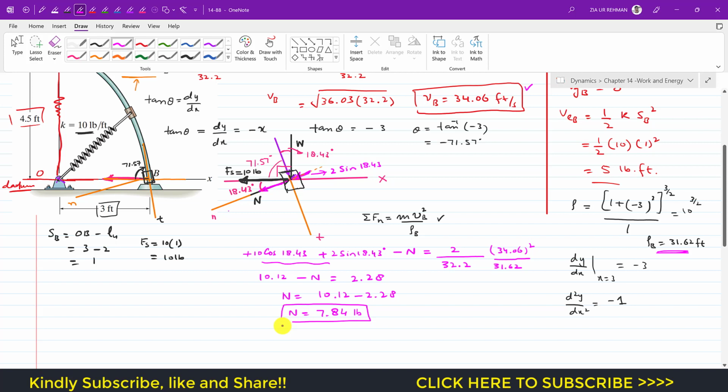Now similarly, if we apply the summation of forces along the tangential direction, this will be equal to m a t. In the tangential direction, we have this cos component of the weight, which is 2 cos of 18.43, acting in the positive t direction. Similarly, this F s will have one component acting in the negative tangential direction, so you will write minus, and this will be the sine component, 10 sine of 18.43, and this will be equal to the mass, which is again weight divided by g value, 32.2, times the tangential acceleration.